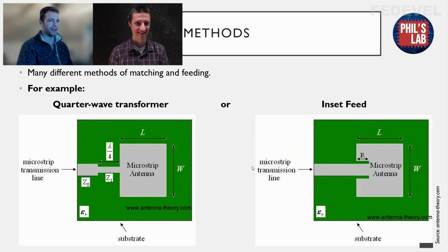Let me just get the first thing right and then see how this thing turns out on the right side. But yeah, you basically have to make these slots in the feed line, and that'll change in some way the impedance properties seen at that edge. Mm-hmm. And reduce the coupling, increase the coupling at certain points, and miraculously it would work, apparently. But basically what I went with, because of simplicity, is this quarter wave transformer.